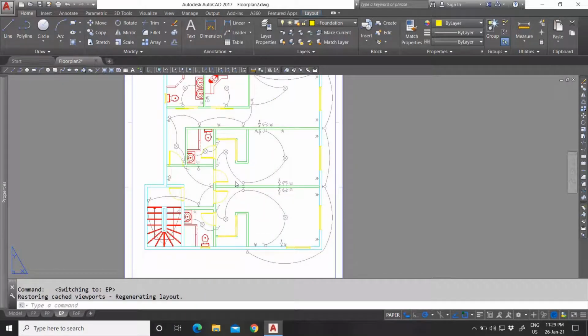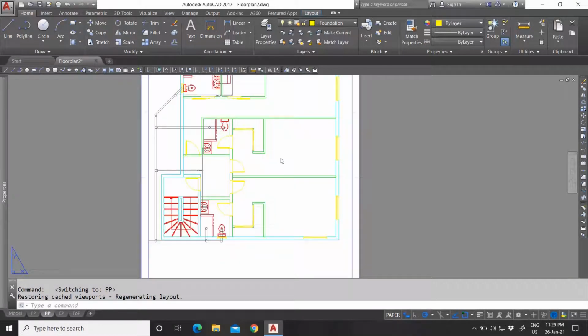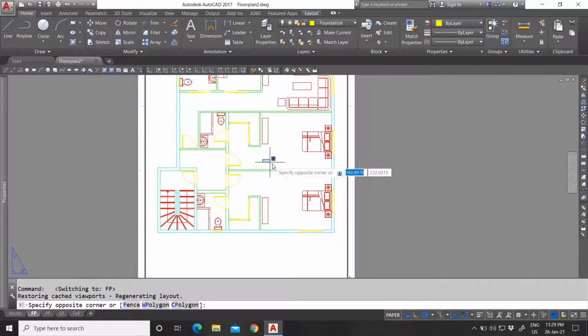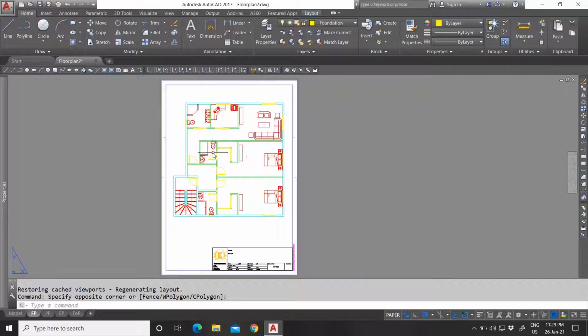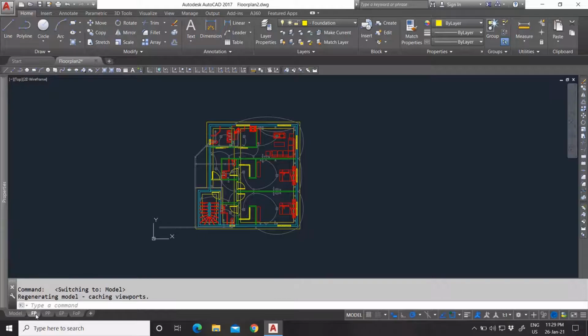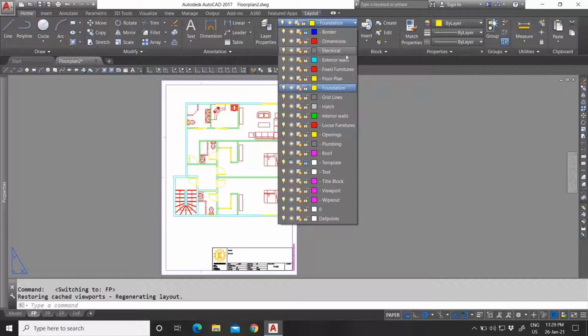my electrical plan, my plumbing plan, and my regular classic floor plan. So that is how you use layers basically. So you can see, even though my drawing here has everything in one, by using your freeze viewport, which is this third row right here, if you go in your layer properties, you can also see it.